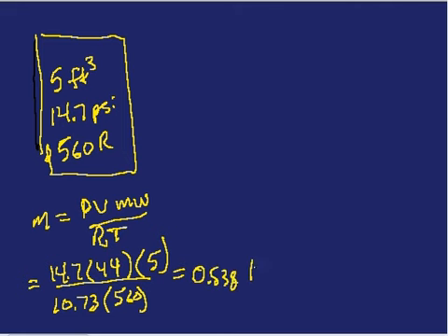Come out with a mass that we had in there of 0.538 pound mass. Now the delta U, the energy balance, is in equals out plus accumulated. Now there's no work coming in or out because it's a tank. It's not moving, the boundary's not moving, so there's no work in or out. We're adding heat to the tank.